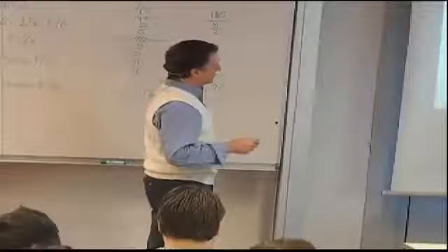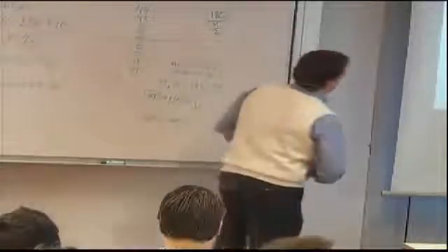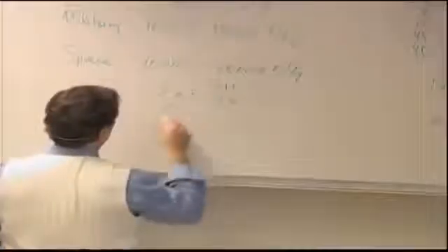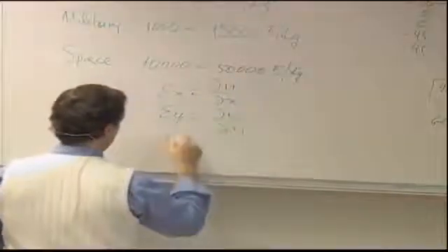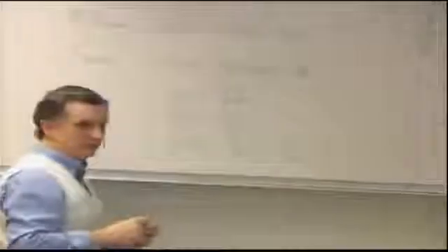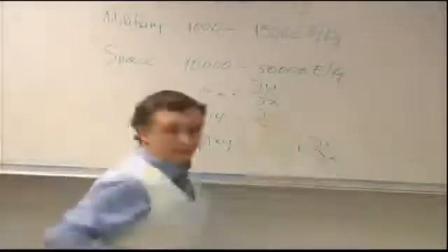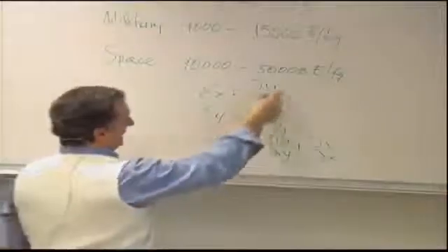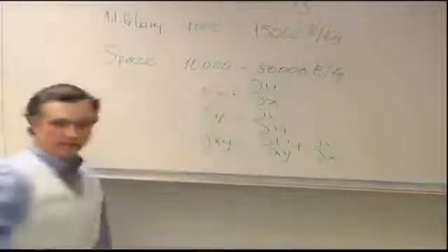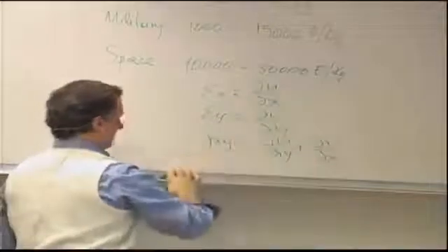So if I solve for the strains from my stress-strain equations, I get these expressions for the three strains. Now, my strain displacement equations. Remember, epsilon x is du dx, epsilon y is dv dy, and gamma xy is du dy plus dv dx. Now, these are three equations in the two unknowns, if you want to call them, u and v. So I can actually eliminate u and v and arrive at a single equation that will only involve epsilon x, epsilon y, and gamma xy by taking appropriate derivatives here. And you can show that, or you can find it in the book, or you can take my word for it. This is the answer.